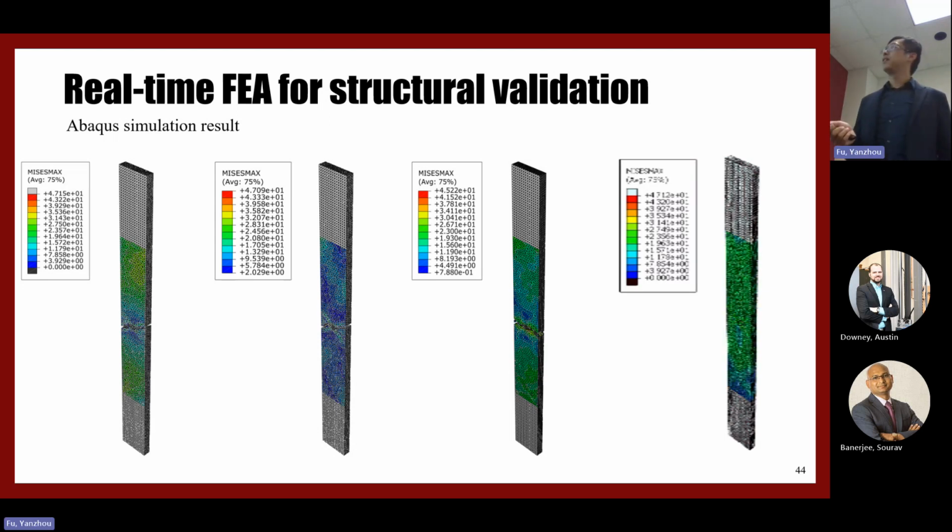Also, you can notice that if there is no impactful defect on the sample, the fracture point is different, and there is one fastener hole defect here, so it will change the broken position.